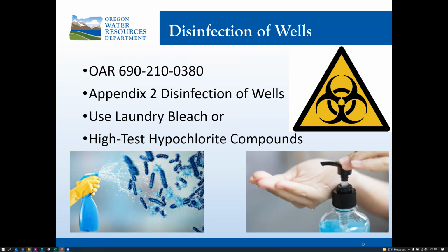The well and its equipment shall be disinfected by thoroughly agitating and mixing in the well a solution containing enough chlorine to leave a residual of 25 parts per million throughout the well after a period of 24 hours. Disinfection should also occur following the installation of pumping equipment.